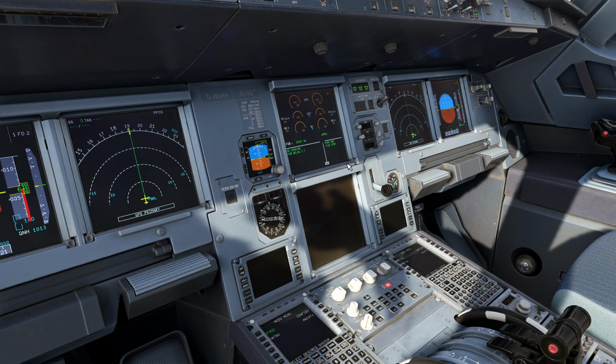This engine warning display is a primary indication for the ECAM section. For this definition, the engine warning display has priority over system display. As you see, at the failure of the system display, there is no automatic replacement of system display on engine warning display. I say again that engine warning display has priority over system display in ECAM displays.